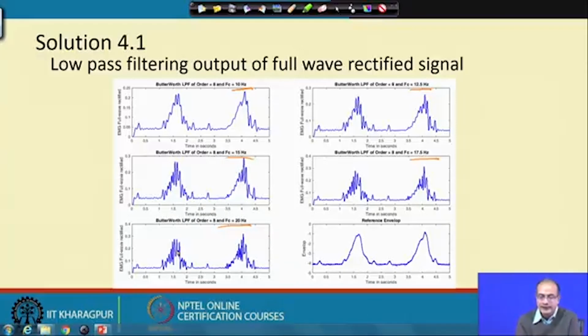So, if we look at these cases, we can easily say that 10 hertz is a better choice of cutoff frequency. Another thing we get is that when we go for the full wave rectifier, the output is closer to the reference waveform provided to us. So, these are the things we get.